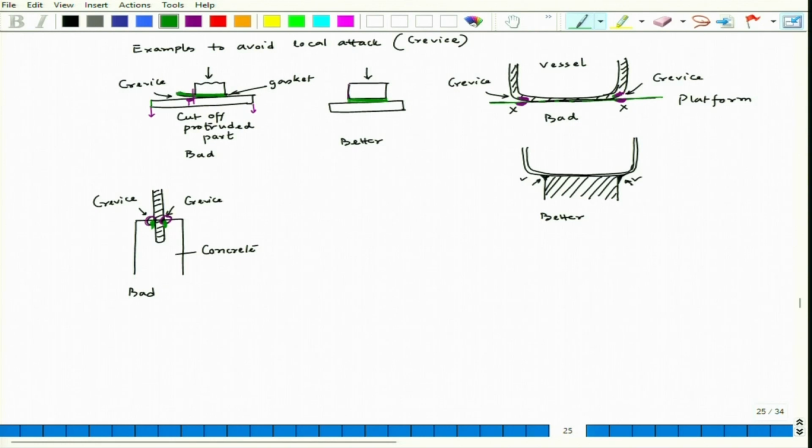And this is interesting because it is a matter of concentration cell. The outside part has a lot of oxygen, the inner part has less oxygen. So, it can lead to a local concentration cell, and the inside part can have a higher degree of corrosion, that means that part is anode.